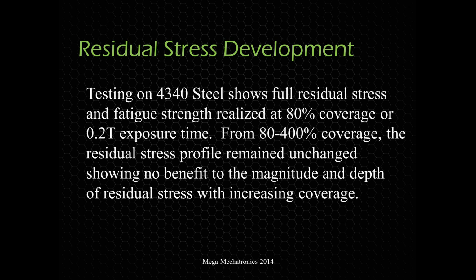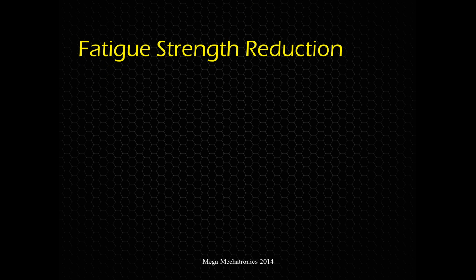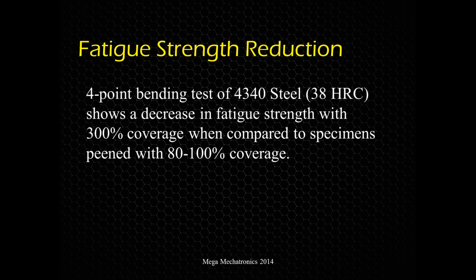So from 80 to 400% coverage, it showed that the residual stress profile remained unchanged, and it didn't show any benefit to the depth of the residual stress and coverage. And again, with another test, the 4-point bending test of the same material, it showed a decrease in fatigue strength with 300% coverage when compared to an 80% coverage. So you can see how leaving it in there longer is actually worse than not even getting full coverage.